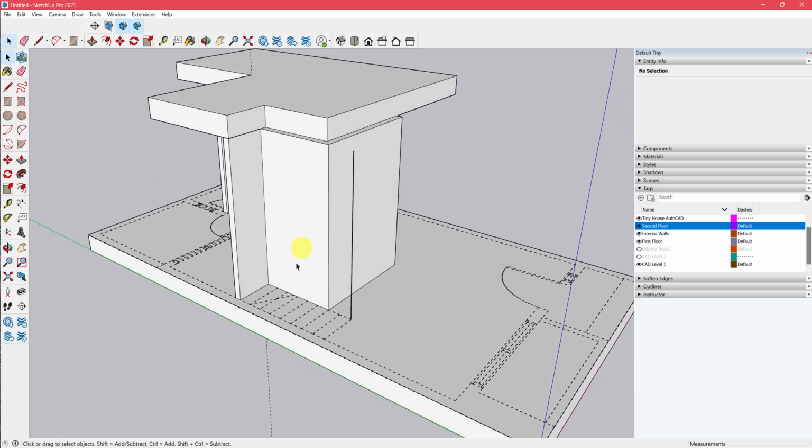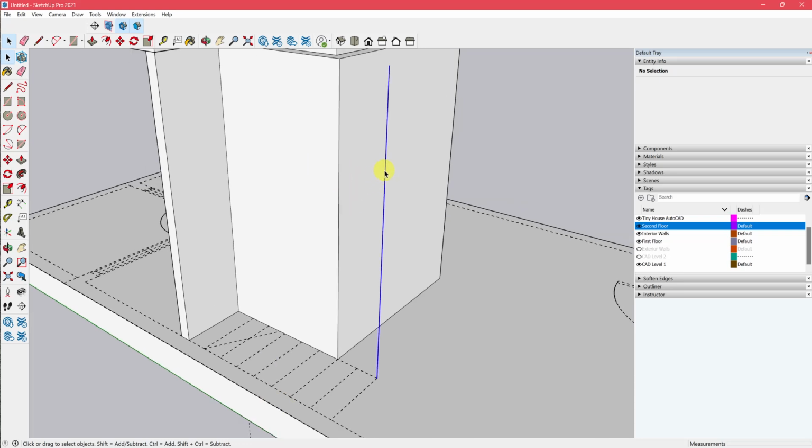And then here's a new little tool. You can divide a line into equal segments by just right-clicking that line, hit divide. As you start to move your cursor up and down along that line, you'll see different points being created. So we want 8 equal segments. You can also just type 8, enter, and it should divide that line into 8 segments. They're all equal, so ours are going to be 1 foot since our line is 8 feet tall.